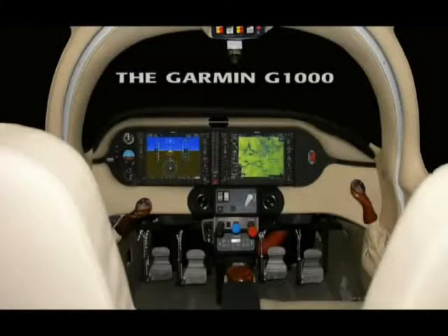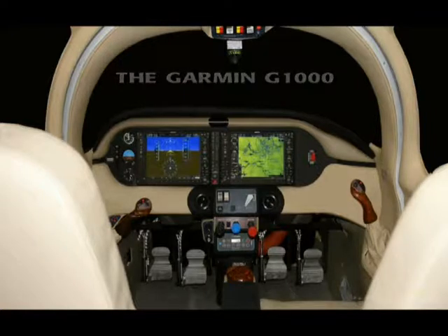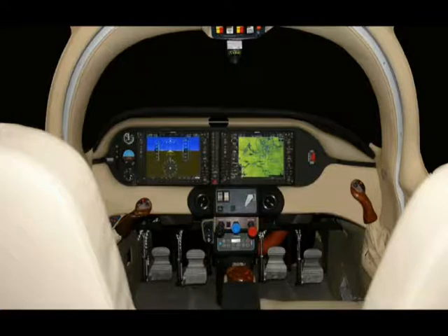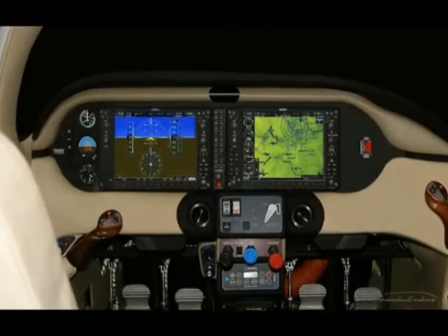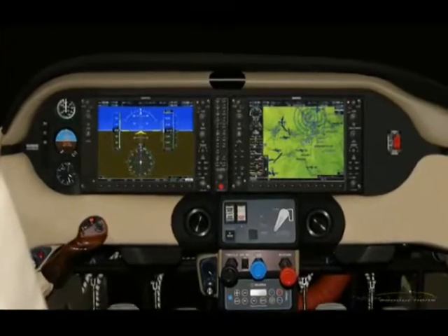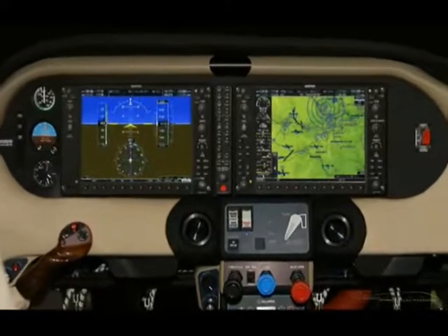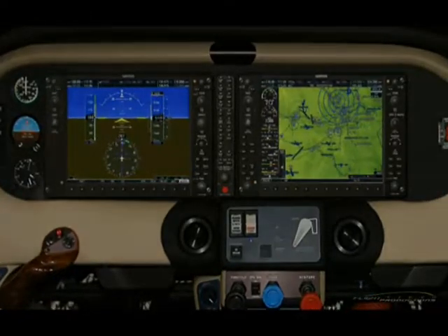The Garmin G1000 is an all-glass avionics suite that can present traditional cockpit information in a single highly integrated system, including all primary flight, navigation, autopilot, terrain avoidance, communication, engine, and aircraft sensor data, all on dual 10-inch displays. The G1000 now features the GFC 700 automatic flight control system with some innovative features that include airspeed hold, overspeed protection, pitch hold, and coupled VNAV.